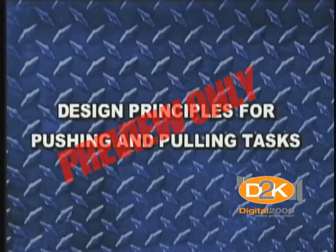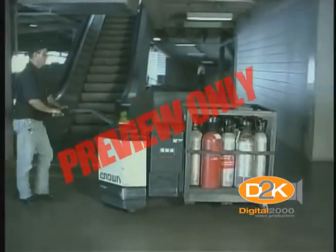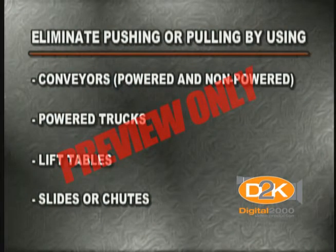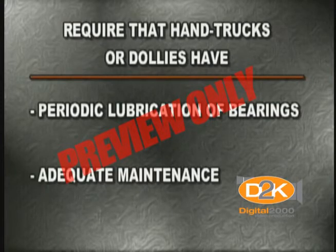It is important that pushing or pulling tasks also be carefully studied to implement ergonomic improvements. Eliminate pushing or pulling by using conveyors, powered and non-powered, powered trucks, lift tables, slides or chutes. Reduce the force required to push or pull by reducing size and/or weight of load, using four-wheel trucks or dollies, using non-powered conveyors. Require that hand trucks or dollies have periodic lubrication of bearings and adequate maintenance.